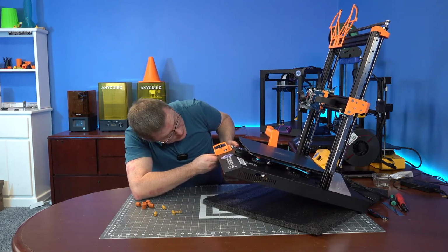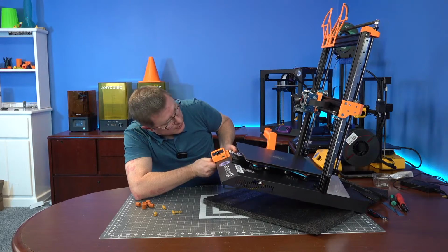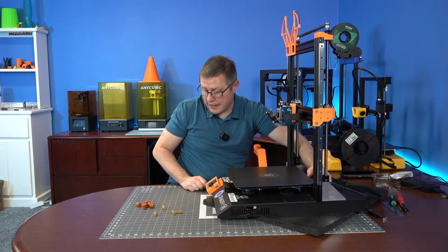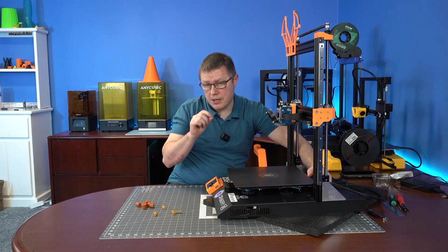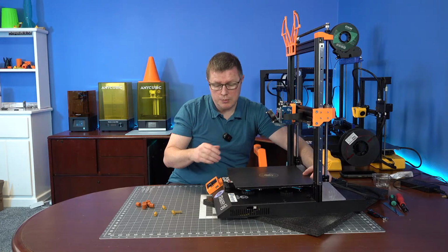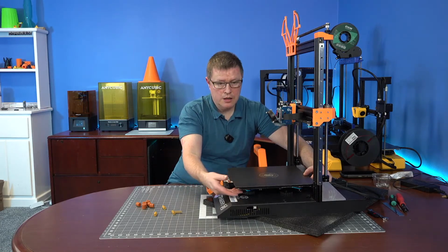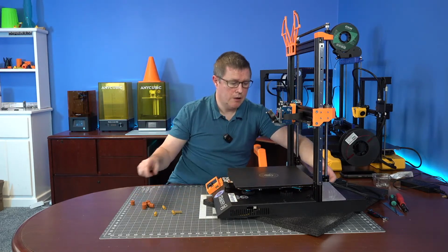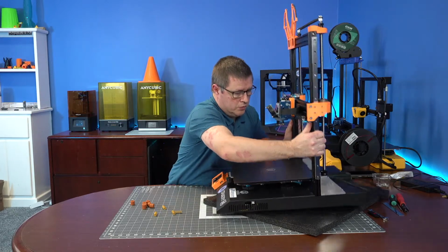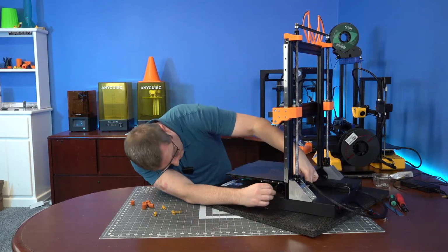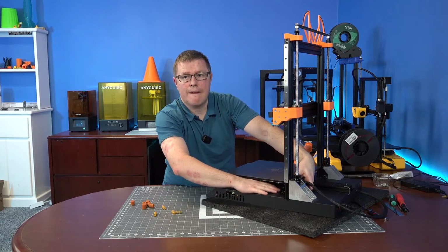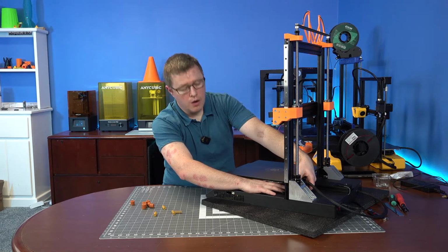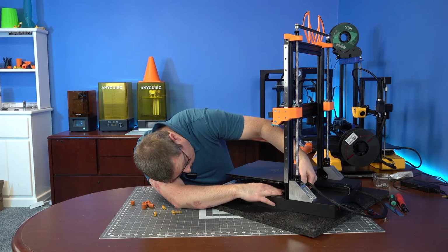Those. Yeah, that makes sense. That could definitely smash into it if you're not careful. We'll see what that looks like. It looks like it's going to be close. If anything, spacers could be printed and used. You put them on the underside between the silicone little spring and the metal carriage plate, instead of up against the glass. Drew says the shorter one is for where the bed heater cable connects on some printers like the CR10S Pro V2. Okay, yeah.